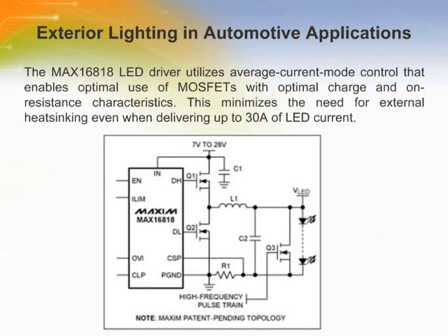Exterior lighting applications raise new issues of security and safety and demands for even more high-power illumination, such as tail lights and emergency warning lights. Tail lights need to be visible over long distance but must not illuminate a wide area. The MAX16800, 16807, and 16808 power supplies are also appropriate for this application.